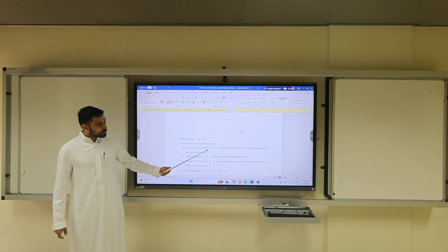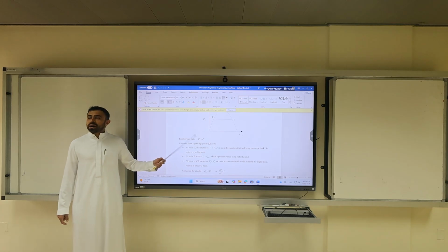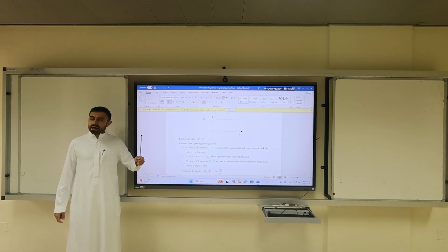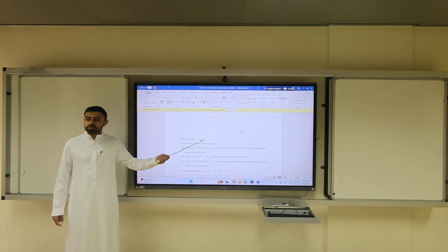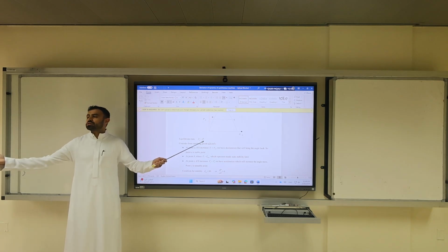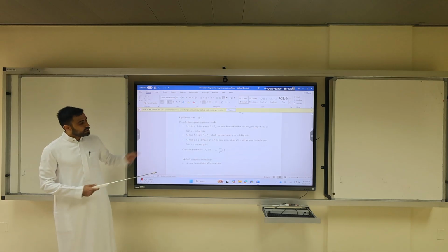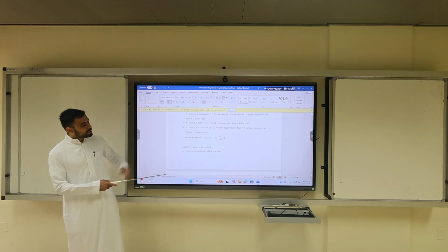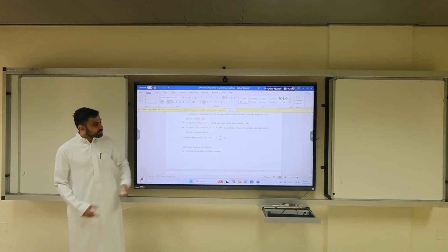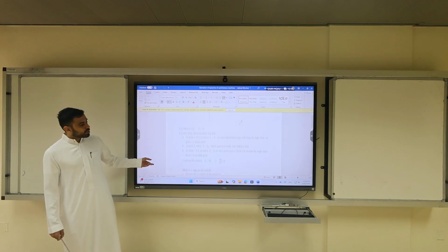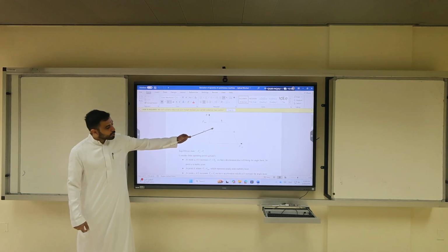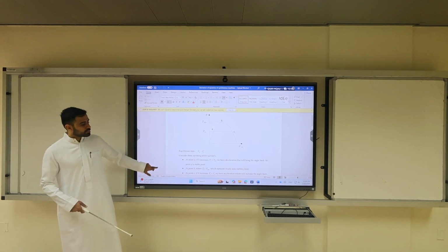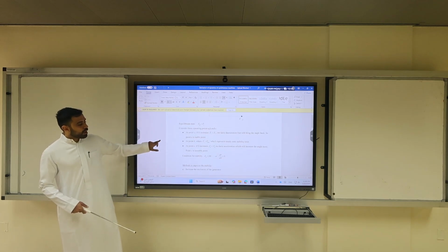So if electrical power, which is the power that crosses the air gap minus the stator losses, copper losses, which appears on the shaft, is equal to the prime mover, the diesel engine, for example. When we have delta increase, our delta P with respect to delta is positive, so it would bring our operating point back to stability region. Okay? The opposite is true.